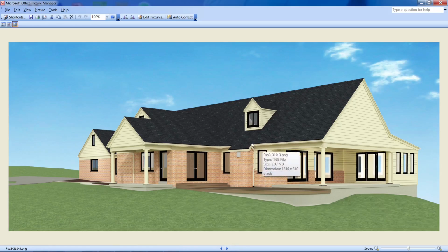And I'm showing a downspout here. Now I got rid of this gutter here because I didn't want the clunkiness of downspouting coming to here. But there is roof splash, and whether they can put a little diverter thing here to keep most of that water going into the gutters will have to be discussed.